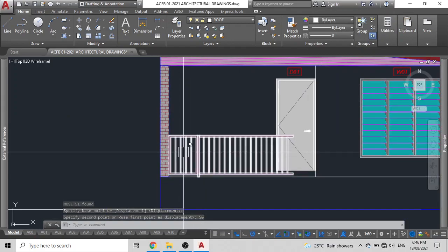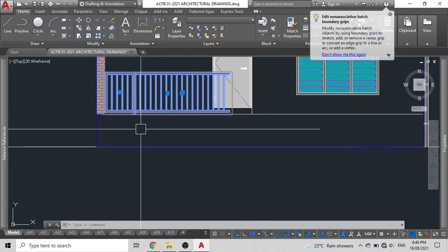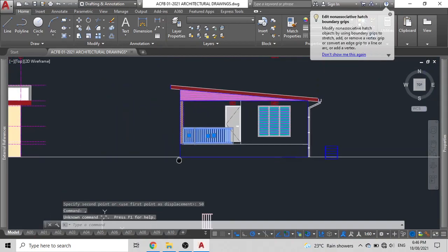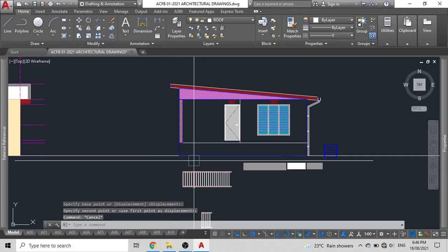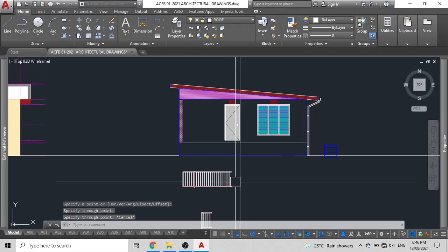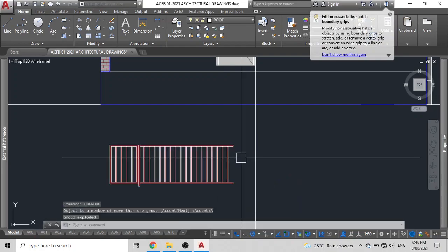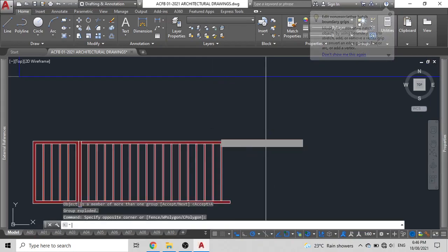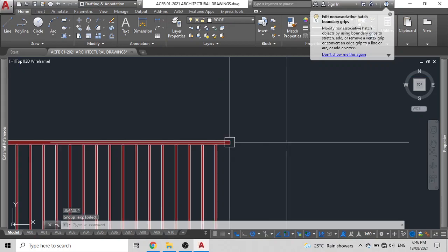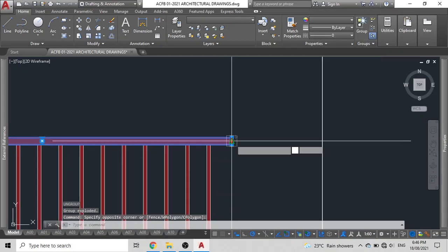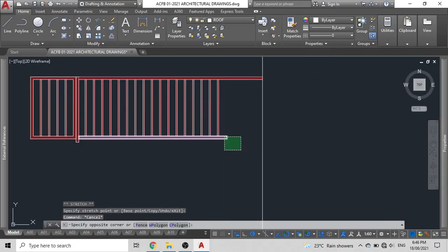So now that you can see that this gate is actually away, so I have designed it to be like so. Now what I'll do is simply move this one down, because my orientation is correct over there. And then I'll draw an X line or construction line. Then I'll simply click on this and do an ungroup, UNG for ungroup, and then accept. Now I'll do the ungroup again, because I had grouped it 3 times, so I had to do that one 3 times. Then I'll pull this line out so that it's perpendicular to that, and I'll do the similar for this.